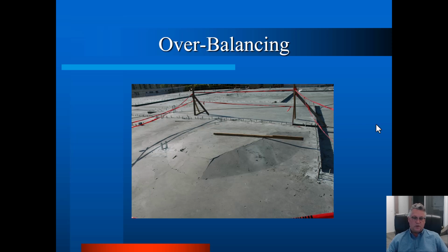You have to make sure that the building is okay and safe and stresses are satisfied even when there's no applied load. The concrete and the pre-stressing are the only load. And this is actually a formed deck, so the drape turned out to be excessive here, an excessive amount of post-tensioning, and it led to a series of these bubbles that popped up across this podium deck. So those are the things to worry about.